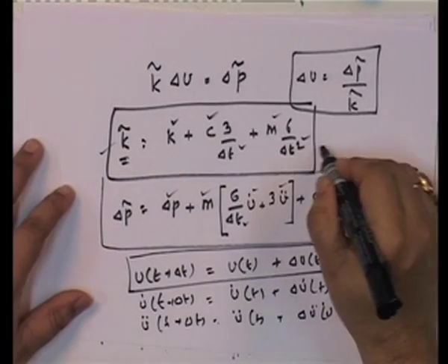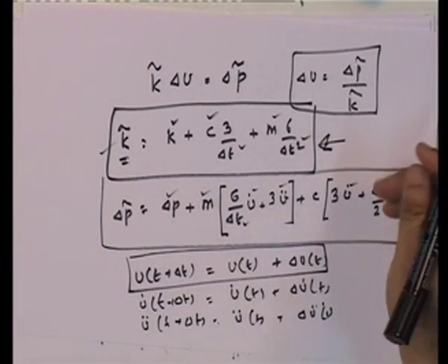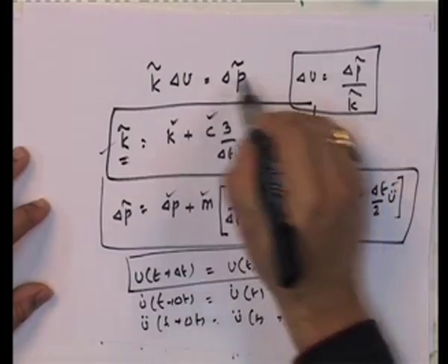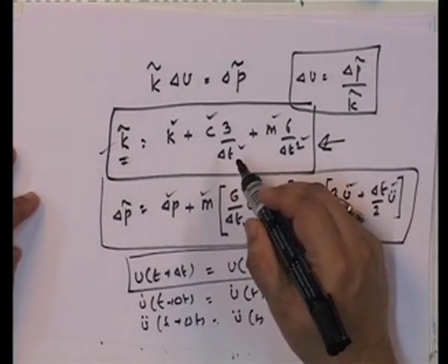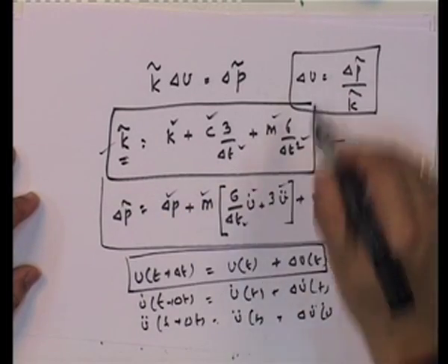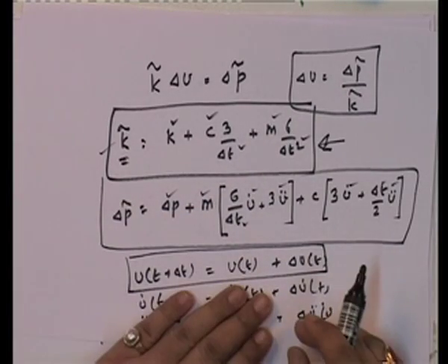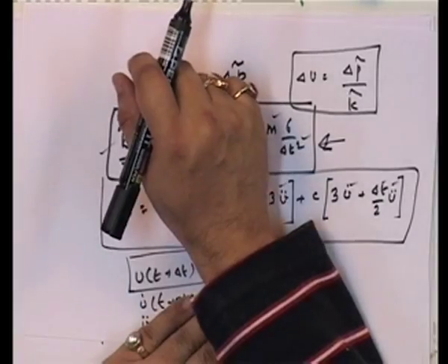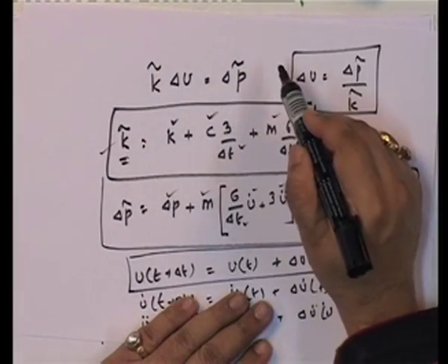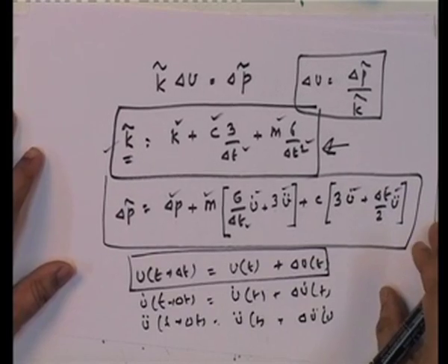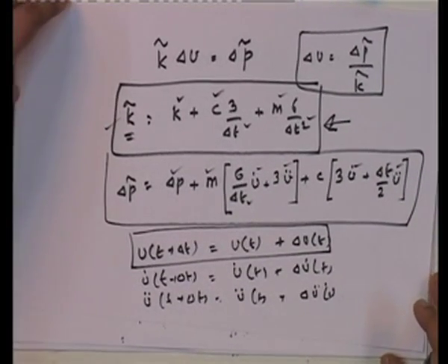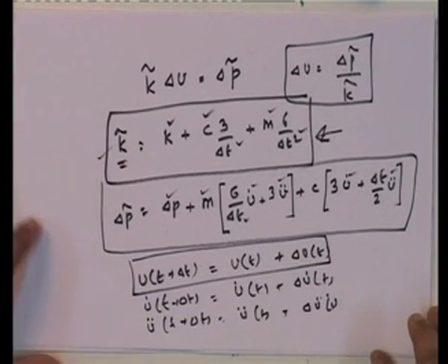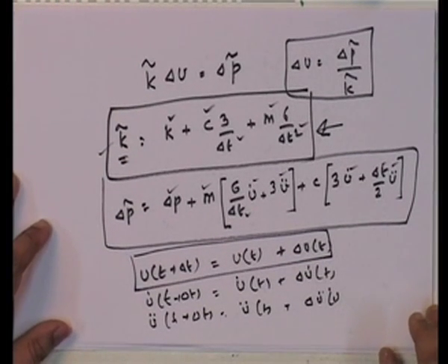So, once you solve, just find k star out once and you do 1 upon k star into these every time step, you find these out, get delta v and then find out this, and then go back, because for the next time step you can do this. So, this is how you solve what is known as time marching, and it can be shown that these are known as implicit methods.